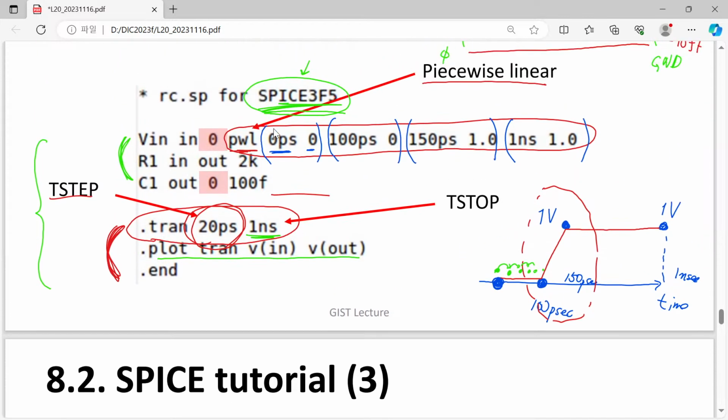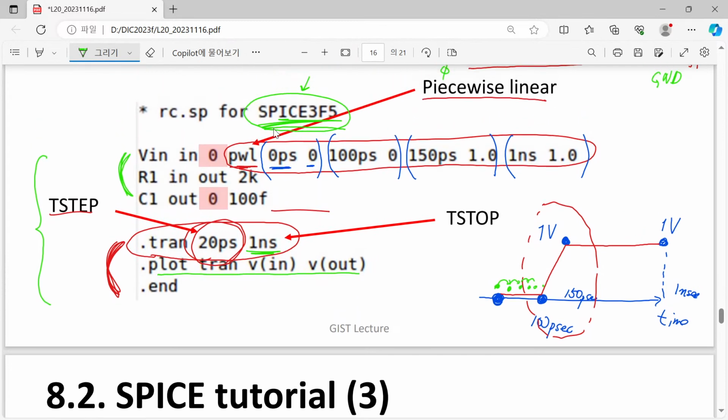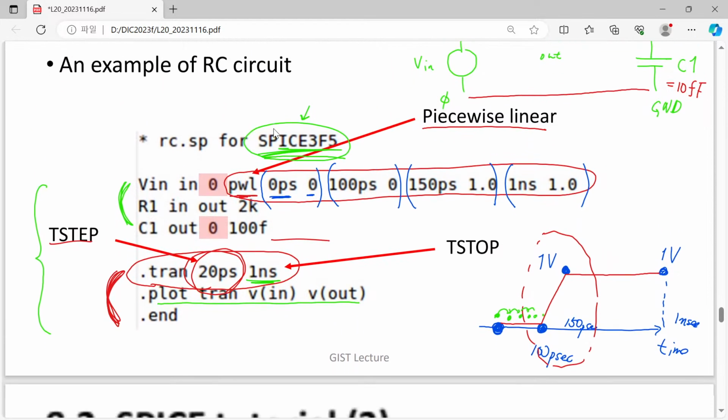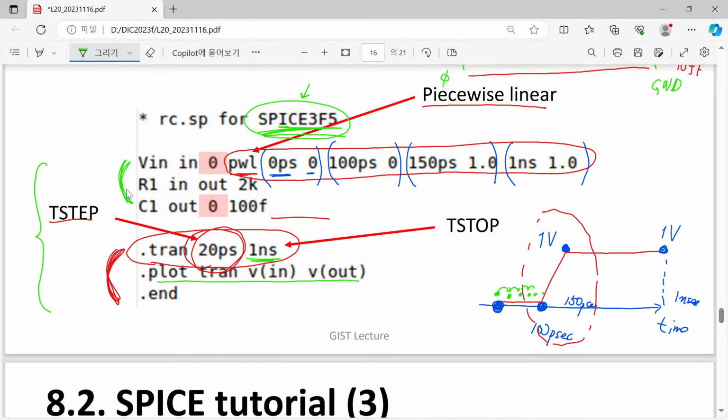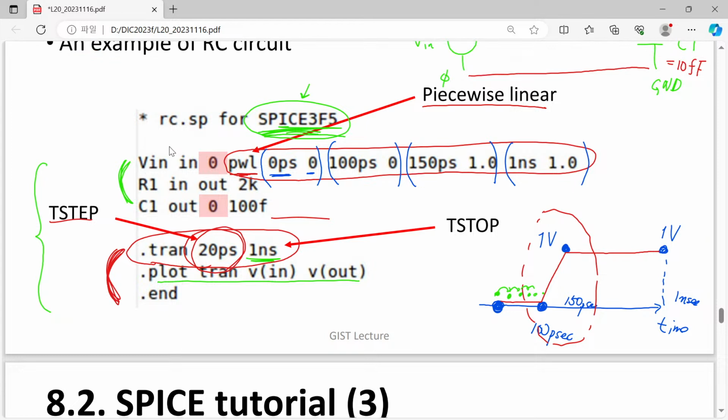And my original intent in bringing up the version is that although we have a certain input file, it is tested for this version. If you have another version like HSpice, this is a different program. Although it is called SPICE, it has much more extended capabilities. So it may have a slightly different specification or additional grammar. So please follow its own grammar. Otherwise, you cannot get the solution.